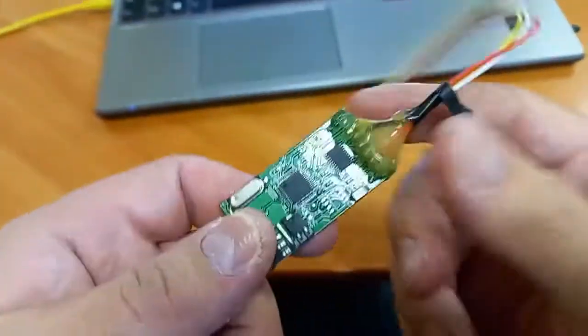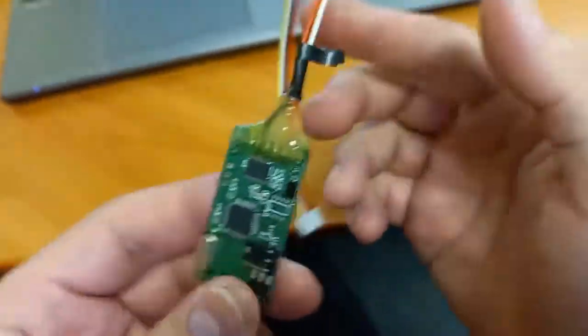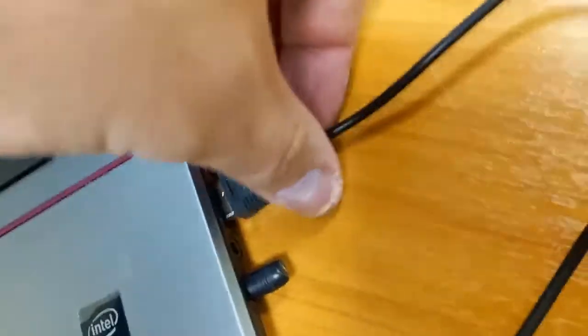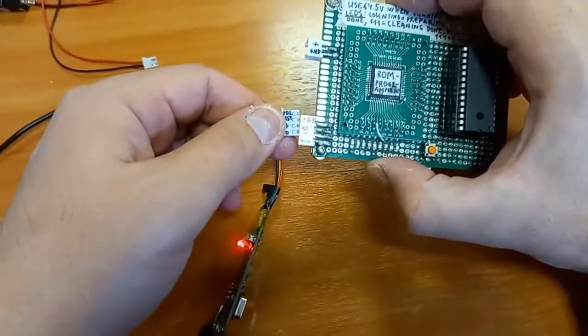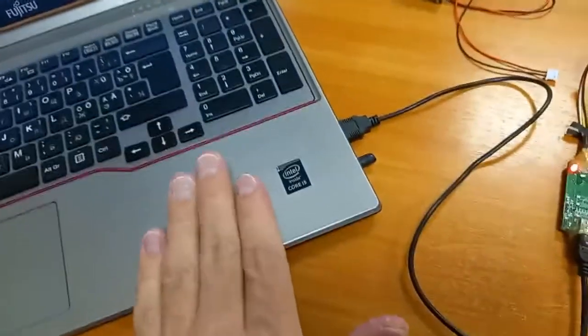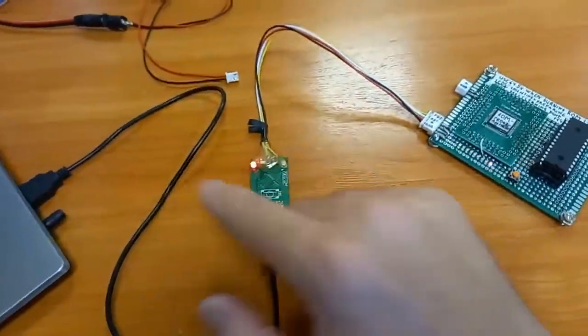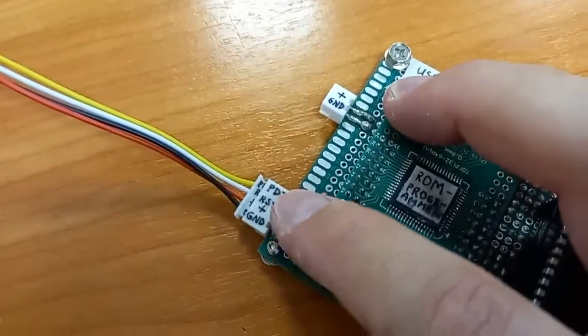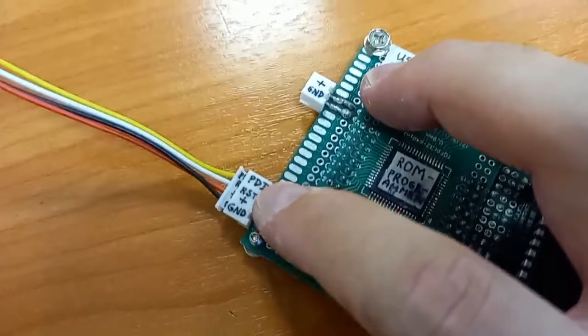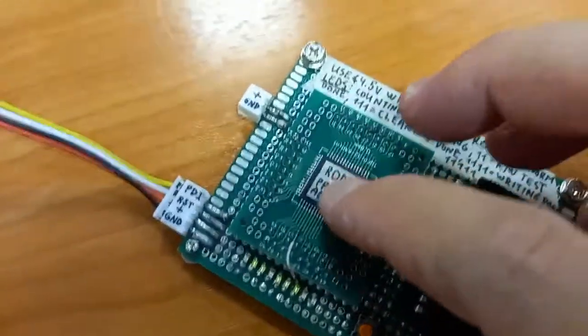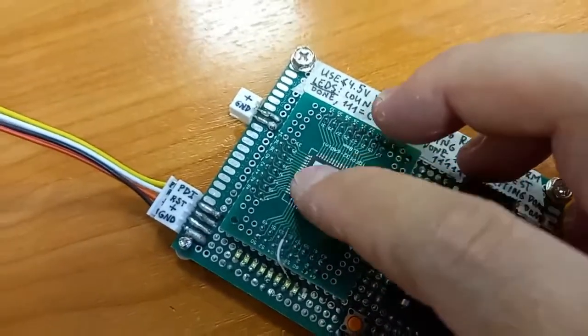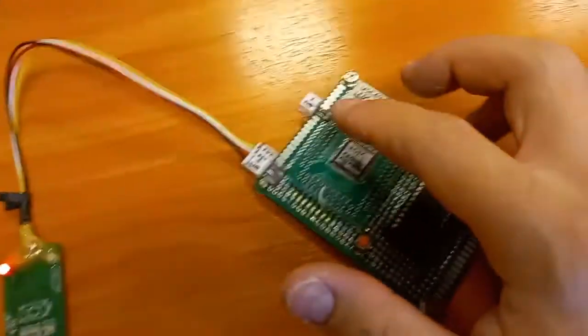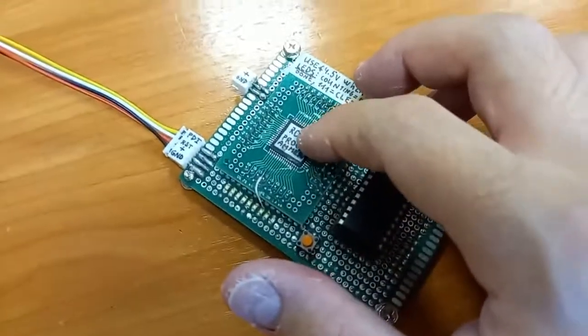His name is USB ASP, a little bit modified. He's going to be like a mediator between computer and controller. So it's going to translate. It has plus, ground, and two wires that are connected to two of the legs for programming this guy. So the instructions on how to write this stuff are going to come here, and it's going to learn how to write our bytes into the memory chip.